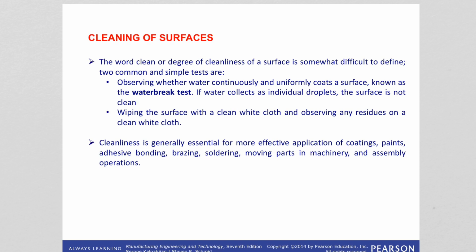Also the type of cleaning process will depend on what type of metalworking fluid you have or contaminants you need to remove. Water-based fluids, for example, are easier and less expensive to remove than oil-based fluids. Contaminants, also called soils, may consist of rust, scale, chips, various metallic and non-metallic debris, lubricants, pigments, polishing compounds, and general environmental elements. So how do we clean up these parts then?